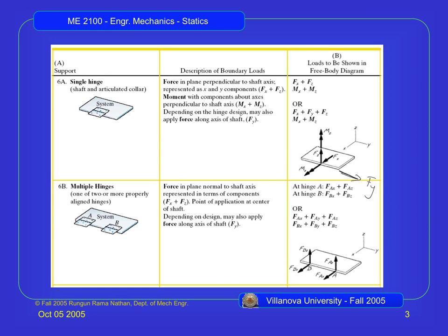So think about the hinge. Here's the hinge, right? Lift it up like this. Stay with me, right? See how it's lifting? Can it rotate this way? No. Because the Mz is there. Can it rotate this way? No. And you can see that with the diagram, with the actual apparatus here. If I were to lift this up, clearly it's rotating about its rotational axis, but I can't rotate it this way, right? That was that one, and I can't rotate it like this, the other two rotational directions. But I can rotate it only about that one axis. That's what a hinge is made for.